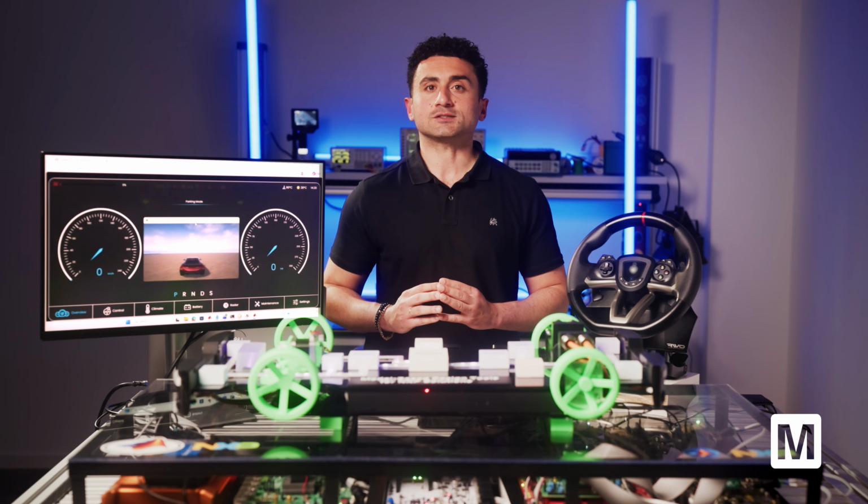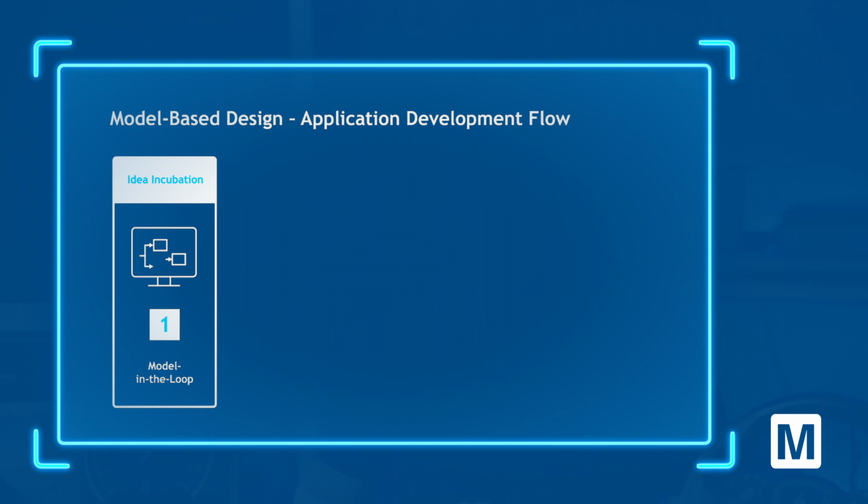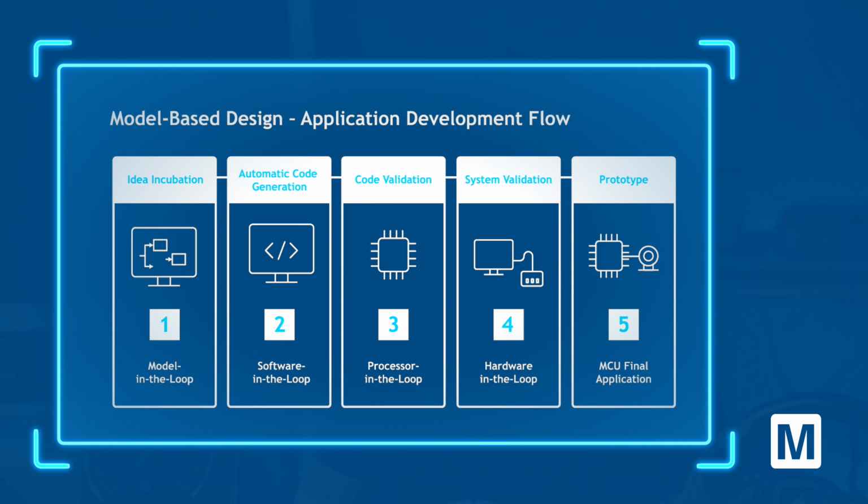What accelerates the development process here is the model-based design. Using MATLAB and Simulink, provided by MathWorks, the application logic is fully modeled and validated at the system level. NXP's model-based design toolbox provides a library of Simulink blocks that map directly to the S32K312's peripherals.